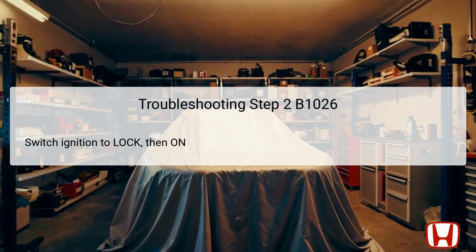In the second step of troubleshooting DTC B1026, the technician should turn the ignition switch to the lock position and then back to the on position. This action is crucial because it reestablishes communication between the vehicle's electronic systems and the HDS. Resetting the ignition helps in refreshing the vehicle's data and may also resolve momentary glitches within the system. It is important to ensure the switch reaches the correct positions to avoid any miscommunication during the diagnostics.